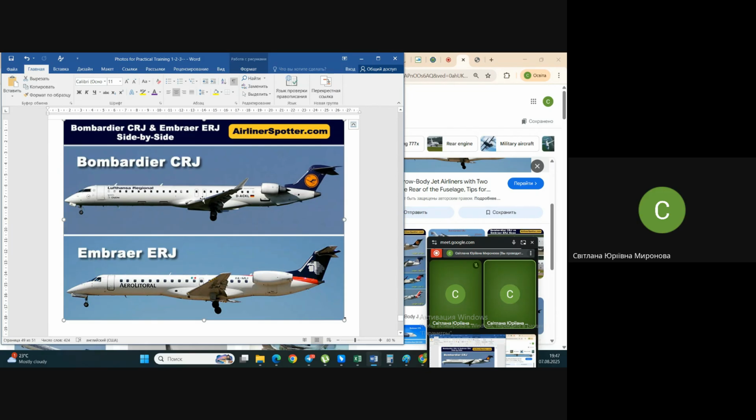By the way, as I said, in case of belly landing, this wing under the fuselage is like one more protective device for the passenger cabin, and additionally it may save some time, increase the time for passenger evacuation from the cabin, and may help passengers leave the airplane safely, for instance, to jump to the wing and from the wing to the ground. While the other emergency exits have additional devices for evacuating people.